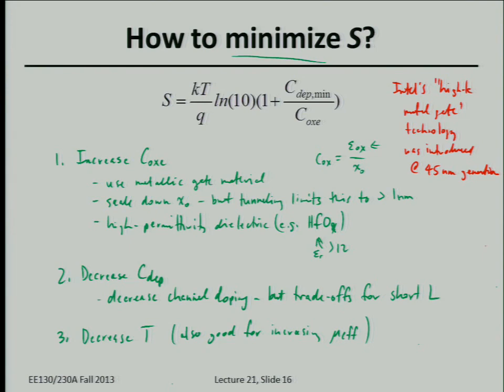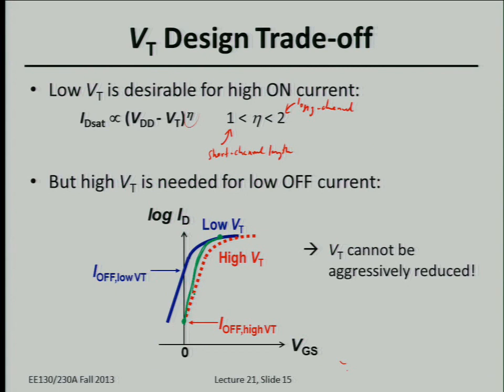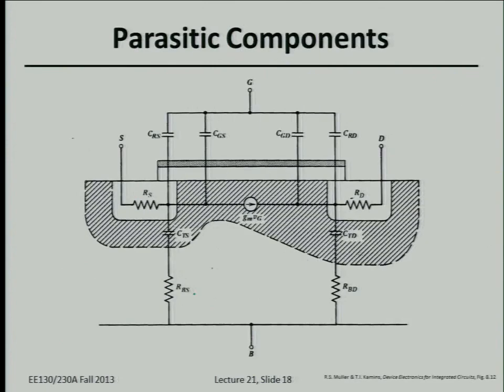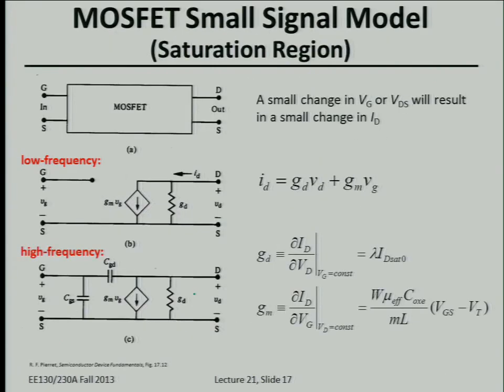So for VT, you have to be careful to optimize the design of your transistor and therefore tune the threshold voltage to meet both the maximum off current tolerable and the minimum drive current required for the required circuit operating speed. So your design project basically specifies that you have to design a MOSFET with 25 nanometer gate length with some minimum drive current and some maximum off current. Okay, so that's for digital logic.